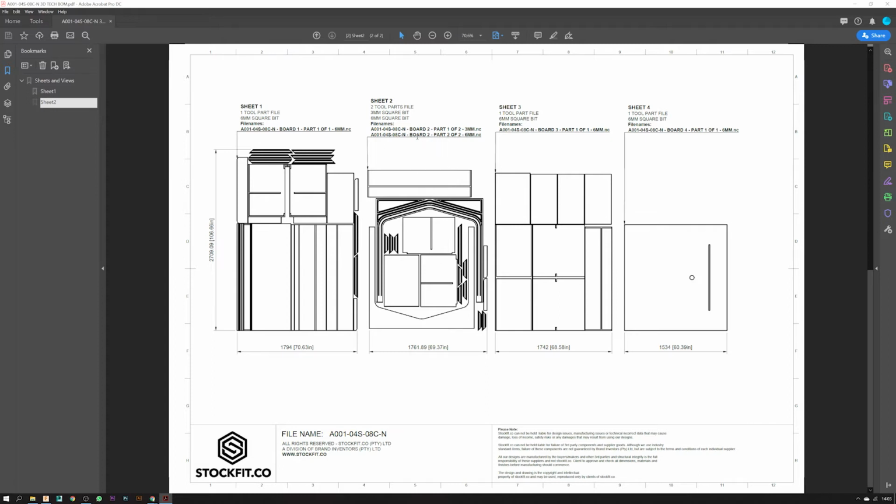So you will load a board and you will run file 1 on the 3mm first, machine it all out, and then you will switch to the second file while keeping the material on the board, load the 6mm bit and then run the 6mm bit to cut out the panel. The only thing is the 3mm bit just does a couple of detail inside corners that you might not be able to do with a 6mm.